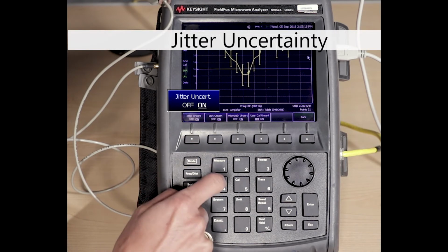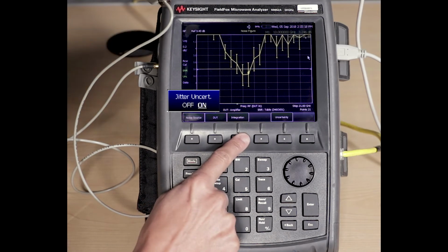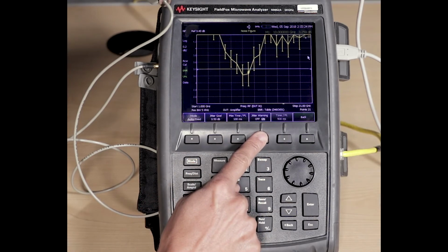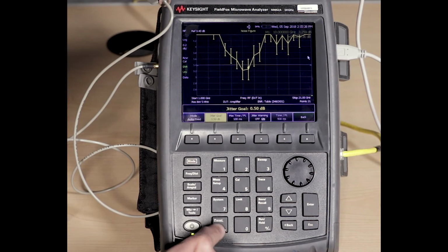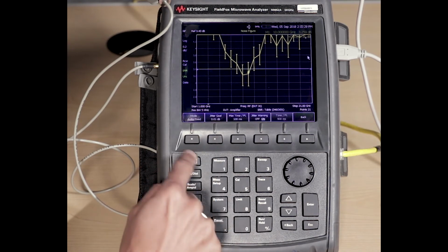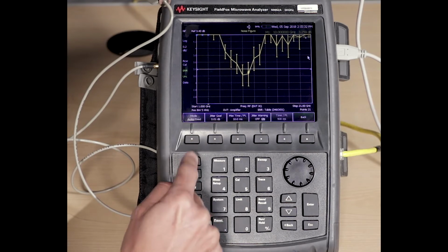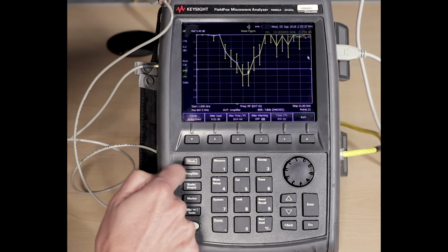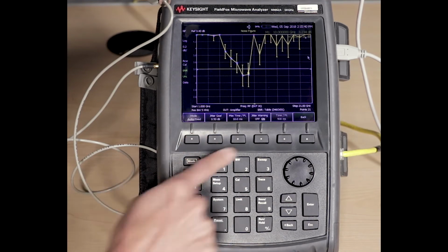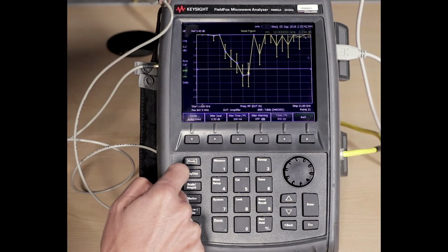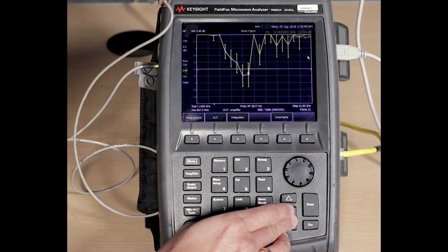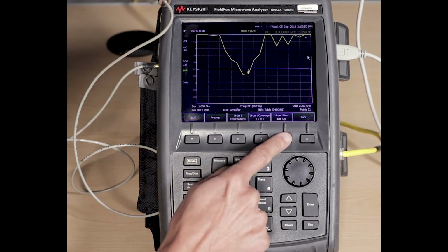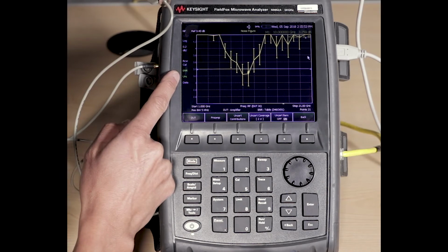Jitter is the one that's very closely tied to your integration and how your jitter goal is set. We also have a jitter warning. Let me set an unreasonable jitter goal, let's say 0.01 dB, and say I want to do it in 0.01 millisecond, essentially 0. These little blue circles that show up say that you're not meeting your jitter goal. But the focus here is uncertainty, so I'll go back to something reasonable here. I should be able to meet my jitter goal then. Uncertainty bars can also just be turned off, or you can have them back on and it shows uncertainty there.